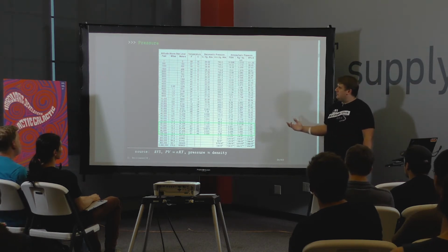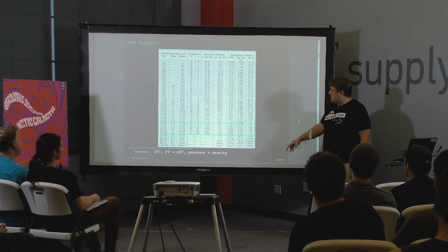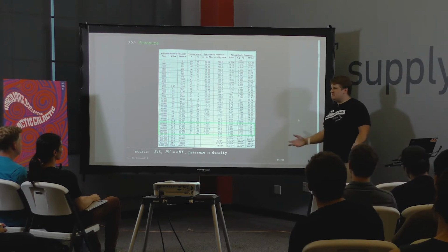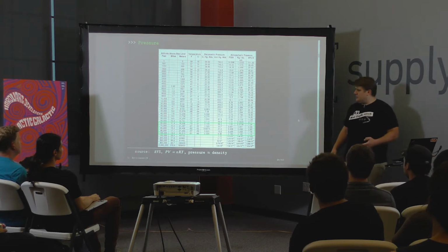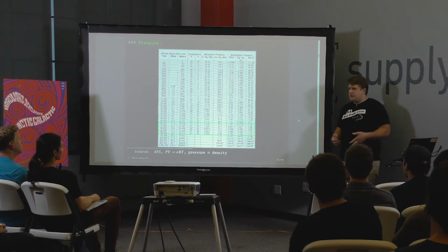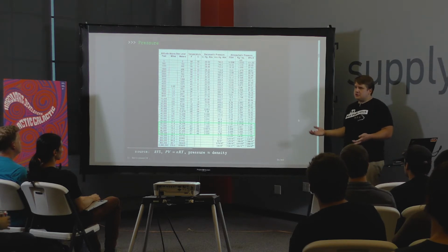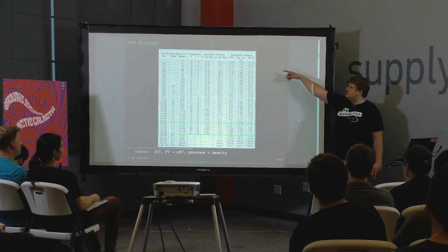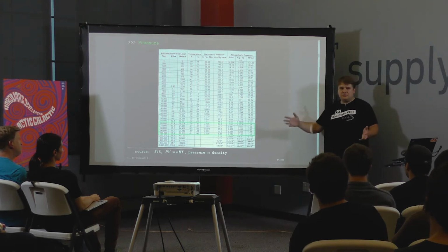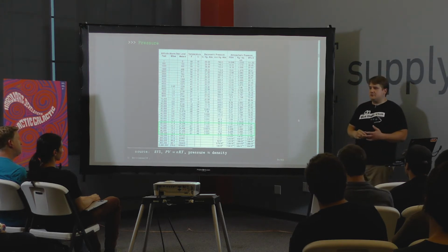Also, when people fly, they don't usually use altitude, they use pressure altitude. So for our stuff, if you just think of 5 kPa, kilopascals, that's roughly 65,000 feet, and it's a good number just to keep in your pocket when you're looking at some of the other graphs. And also, from the ideal gas law, at a constant temperature, the pressure is proportional to the density of the gas. So we're going to get a little bit lower in temperature, but roughly if you're at 5 kPa versus 100 kPa at sea level, with some hand waving, you're at maybe 5 to 7% of the atmosphere, which will impact things like convection.